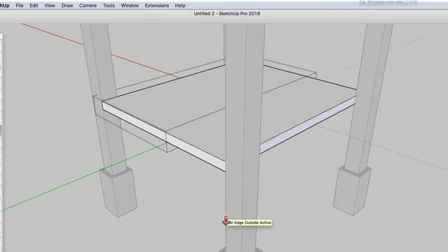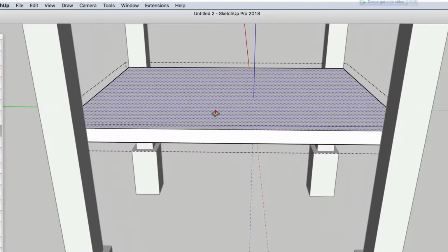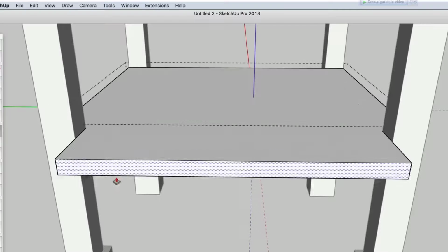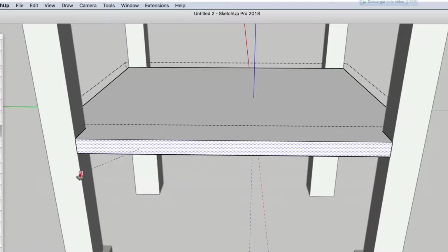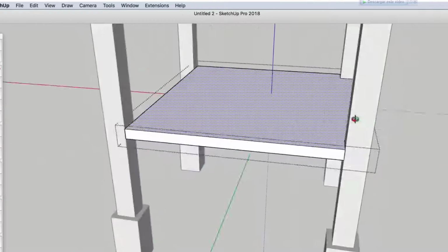To finish the platform, navigate to this side. Make sure we are still in edit mode and draw a rectangle using these intersection inference points. This splits the surface perfectly on the inside of the pillars so we can pull it out and again infer to the pillar for an exact distance. Do this on the other side as well and close out of editing the platform.